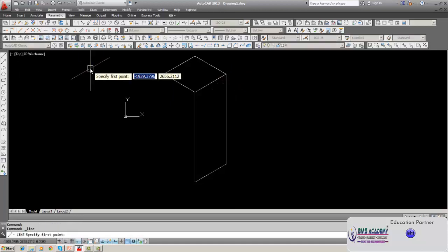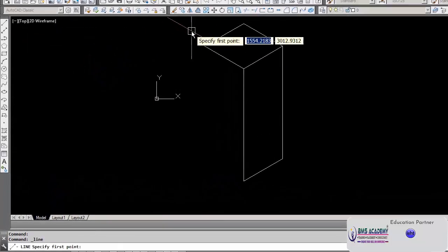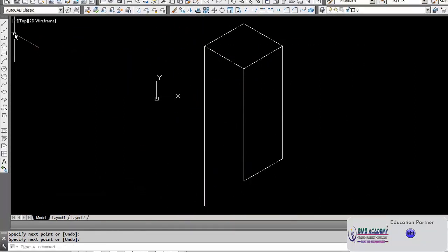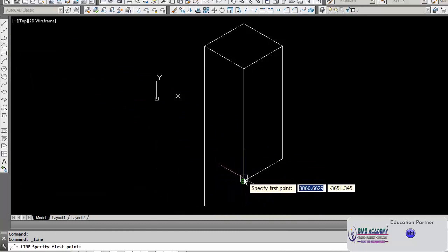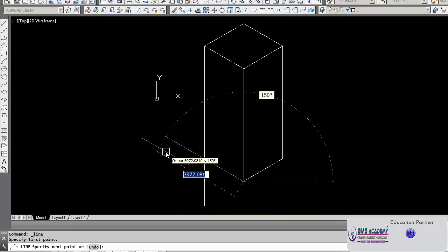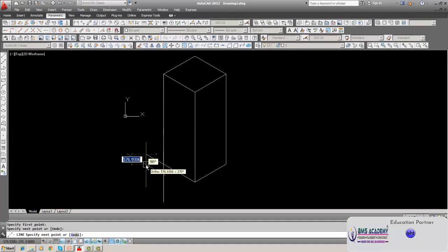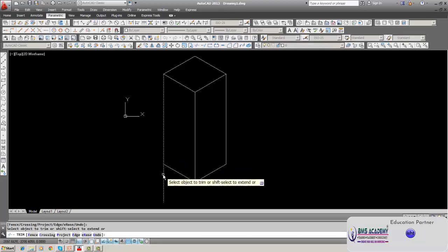And for the other one, you have to press F5, this side, the left face, draw here, like this. And then you can join the point, because it automatically moves parallel to the top line. See, this line becomes parallel. Then you can use the trim command to remove the unwanted lines. This is the cube.